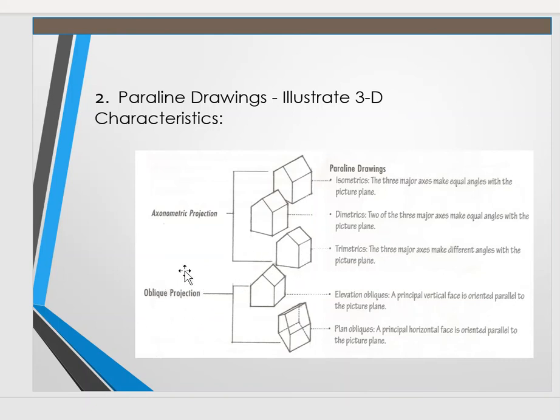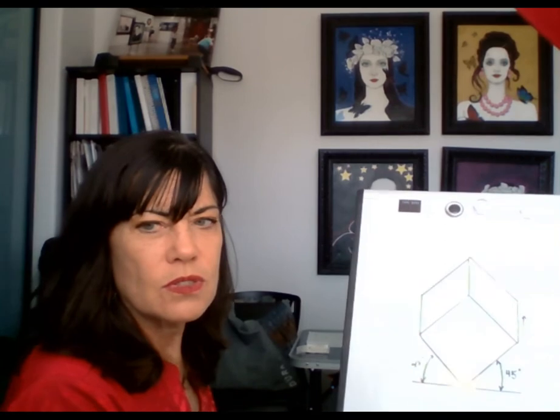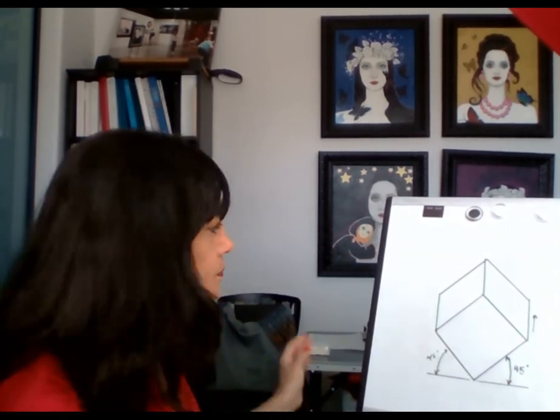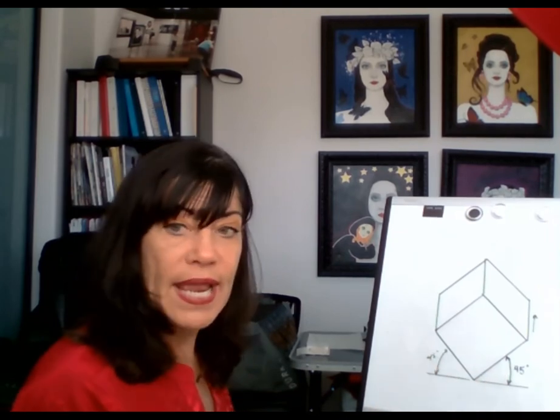Now, an oblique projection is simple. You just take a plain plan view and you extend lines at a 45-degree angle, and basically you're elongating the item. Or you could take this simple object and rotate it and bring up the lines like I have here. So when you see this square, I just tilted it at a 45-degree angle.